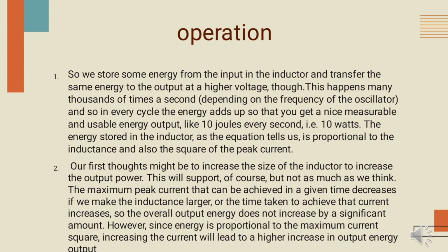Next, we move to the final details on the boost converter operation. The first one is the oscillator. You cannot keep the MOSFET output switch on forever. No inductor is ideal; they have a saturation current. If we did keep the MOSFET switch on for longer than a few hundred microseconds max, the supply will be short circuited and the inductor insulation burns off, the MOSFET goes burst and other nasty things happen.